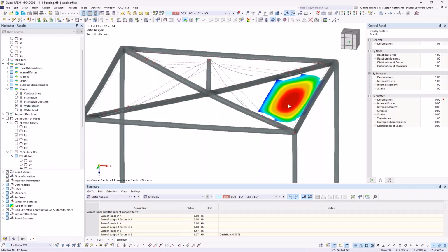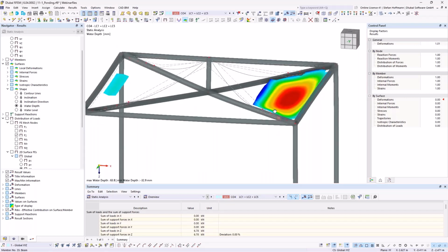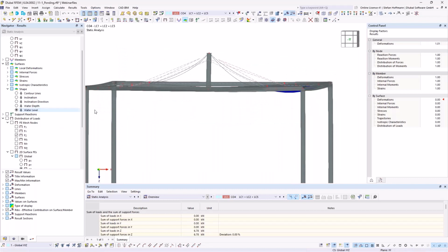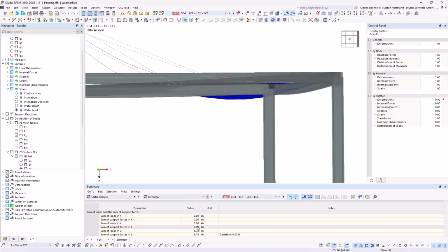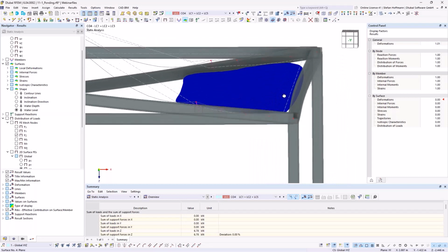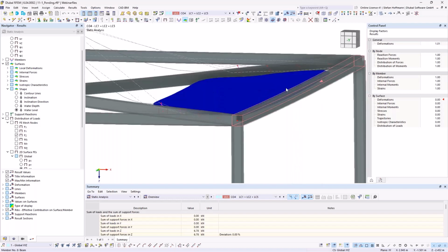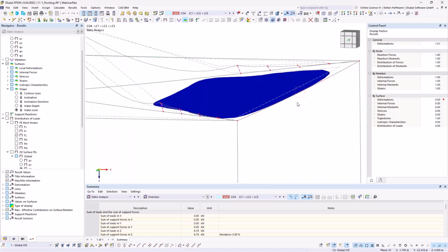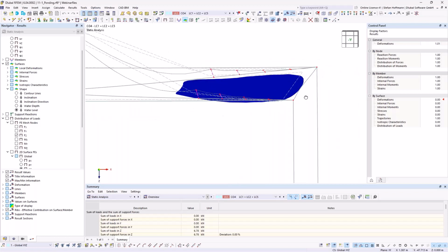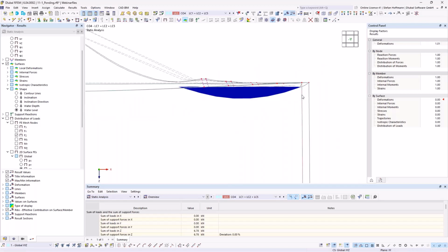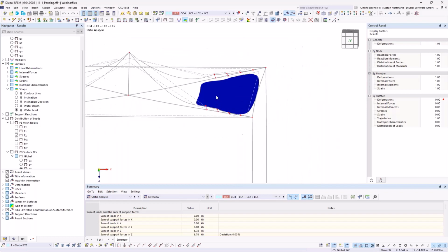and if I increase the precipitation, so switch to the next combination, you can see that it will accumulate even more. And last but not least, it will even fully fill my hole, and I will then receive a final result. It will not influence the membrane with its stiffness and the pre-stress more, because it will afterwards just drop down at the edge, as you can see over here, where the member is a 1D element, so it will not take into account the height of the member. That's not possible in a 1D, but it will now flow down, and this is then the state of equilibrium.